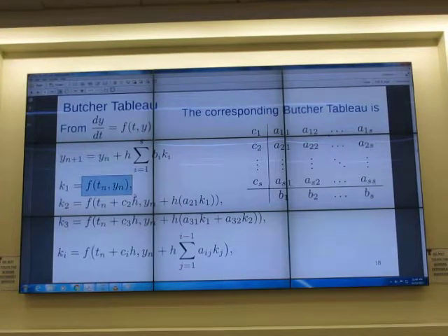So now you cannot think about k1, k2, k3, k4 separately anymore. You think about having 4 equations, 4 unknowns, right? And we can calculate the Jacobian matrix. We solve with the Jacobian matrix, then we can solve the system of nonlinear equations. Then we kind of invert the matrix. We solve everything simultaneously. Then we get k1, k2, k3, k4. If it is fully coupled, fully implicit. Good.